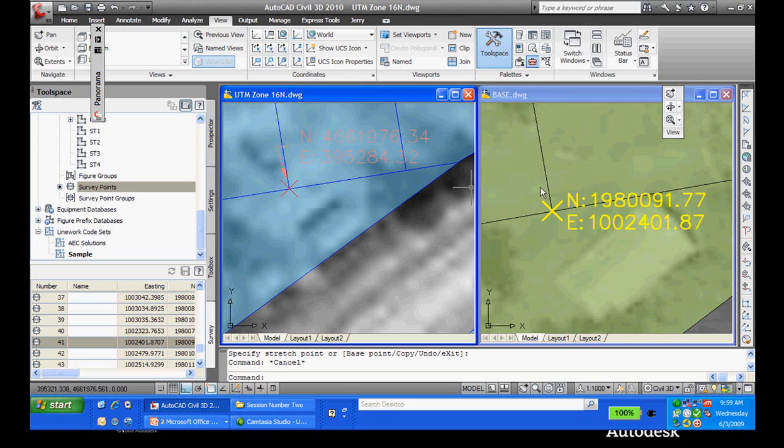Well, if I had a municipal's drawing and they had utilities that were shown and I wanted them on my system, I would need only create a database. Once I have a database, I don't need to convert theirs into anything. I can just go to figures within my database, say create from drawing, select those objects. They'd now be defined in my database, and then I just drag them into my drawing and they'd be transformed.